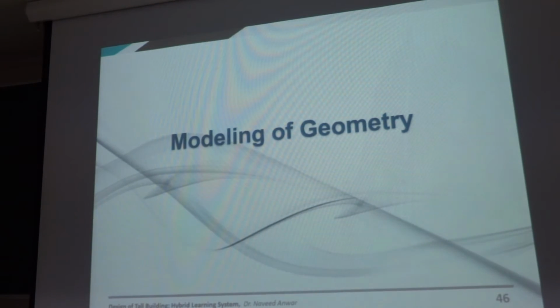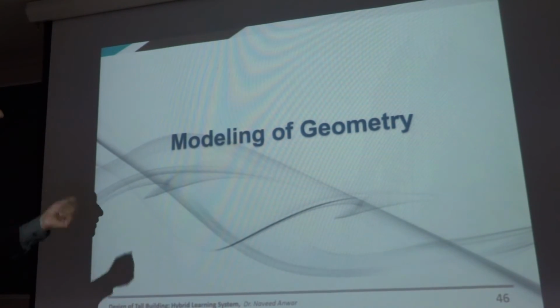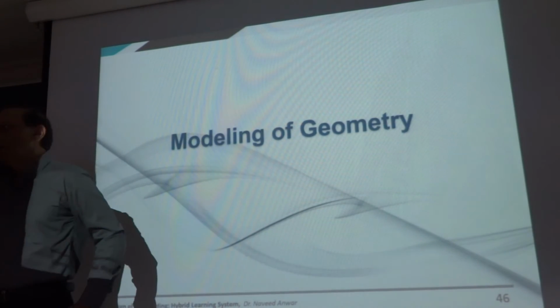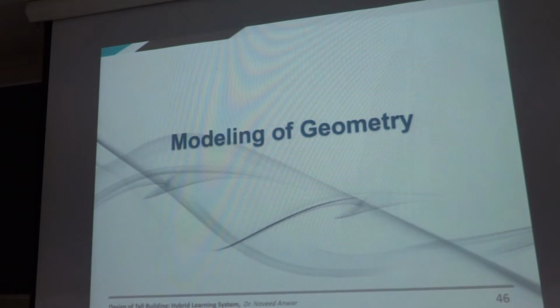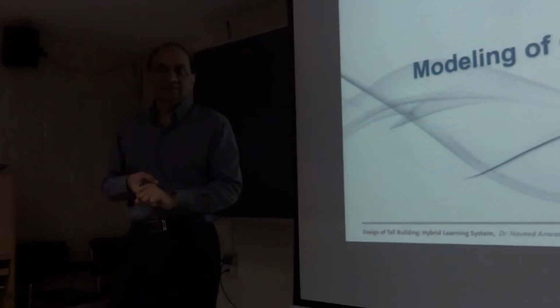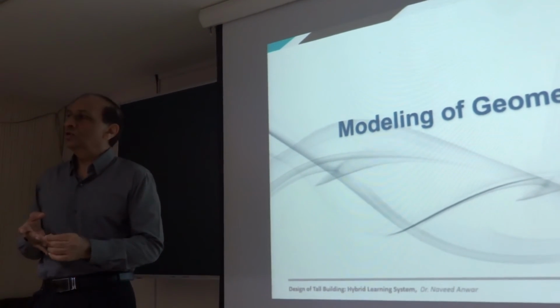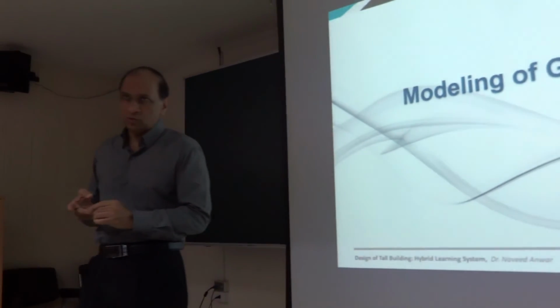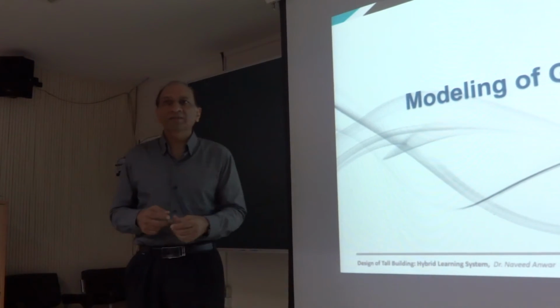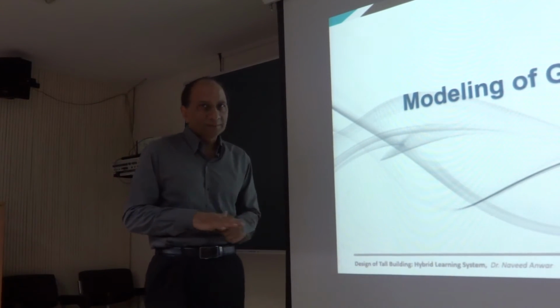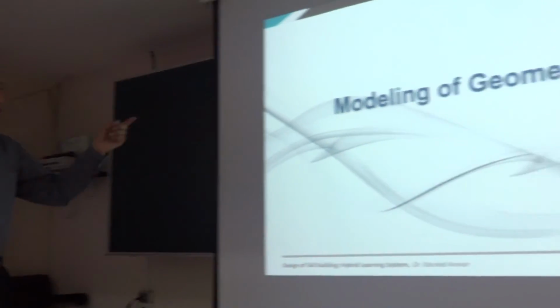Now let's come to a slightly higher level issue. Material, as we know, is a difficult thing, but we must just remember three important things. The ability to model isotropic, orthotropic and anisotropic materials, right? If you're using an element which is only one-dimensional, you have no choice but to use isotropic, two-dimensional, orthotropic, three-dimensional, anisotropic. Okay? Now let's come to the geometry.